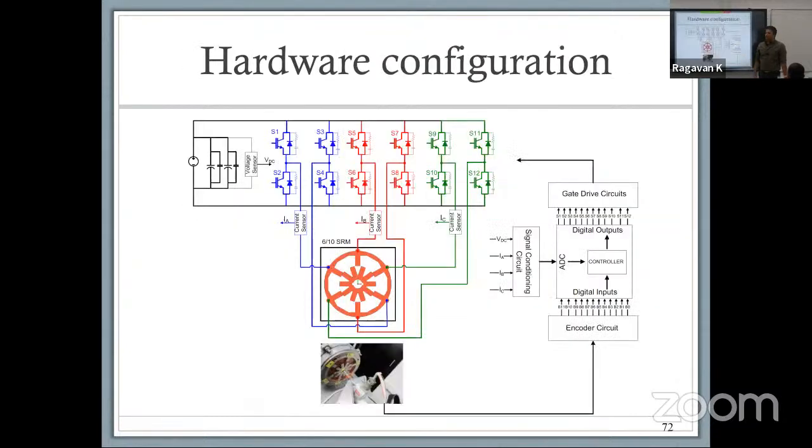But what we did specifically that was beneficial for us was being able to embed, and this is some time back, the simulation model of FEA into Simulink. And that gave us substantial benefits in identifying how this system operates. What we have here in our case, we actually used 4 full bridges. We were trying to identify the best control. The original design we did was a sequential design, which means we designed the motor and then we designed the controller. That's the thinking that we changed a little after that.